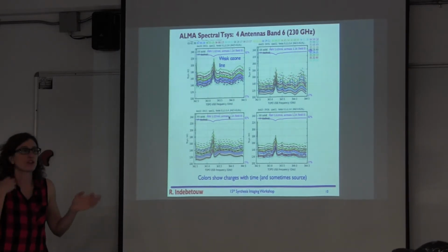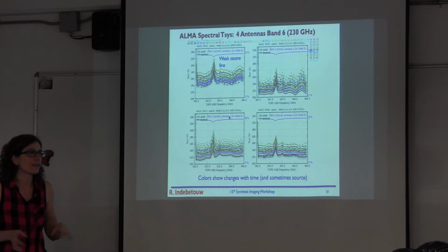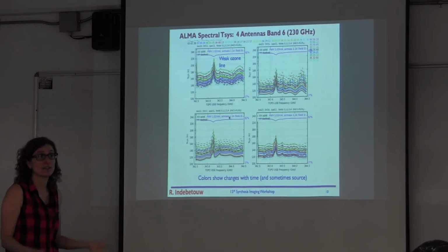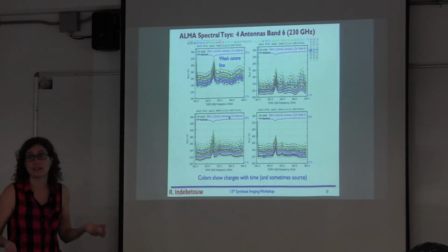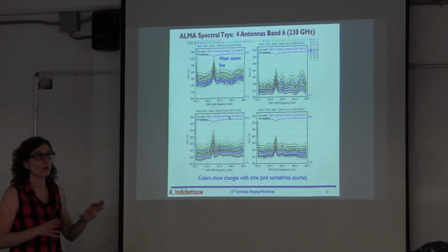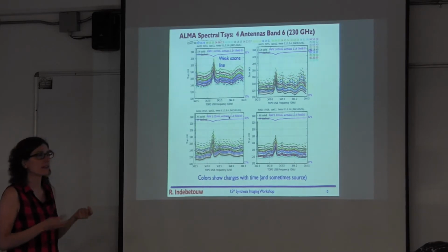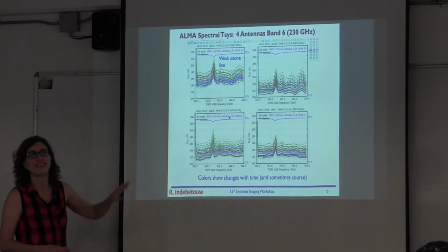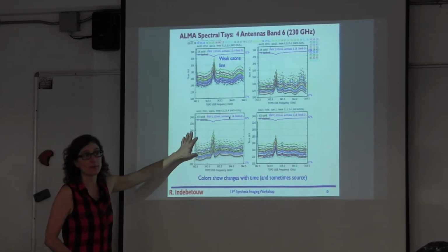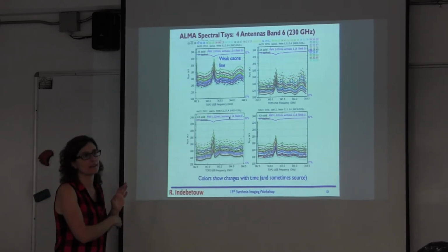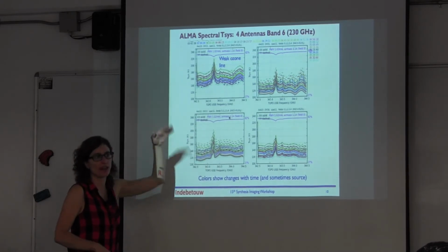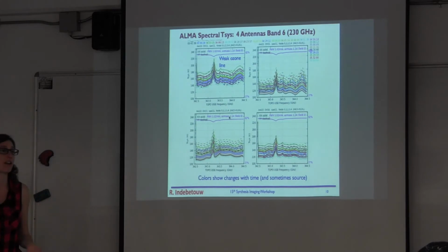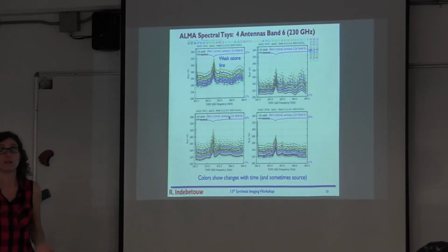Of course, yeah, this correction might be good or bad. If the antennas are very noisy and you divide by that factor, what happens? Your visibilities go up like crazy. So the pipeline checks these results in order to flag antennas. If an antenna is very bad, it's behaving very wildly, you drop it out, because it's going to add a lot of noise and the amplitudes will be very, very high.